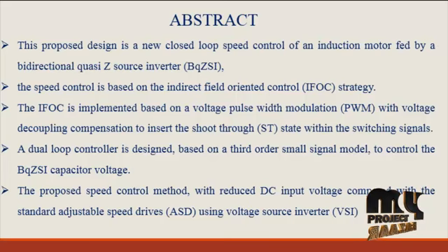The proposed system design is a new closed loop speed control of an induction motor fed by a bidirectional quasi Z source inverter. The speed control is based on the indirect field oriented control strategy. The IFOC is implemented based on a voltage pulse width modulation and with voltage decoupling compensation to insert the shoot-through state within the switching signals.